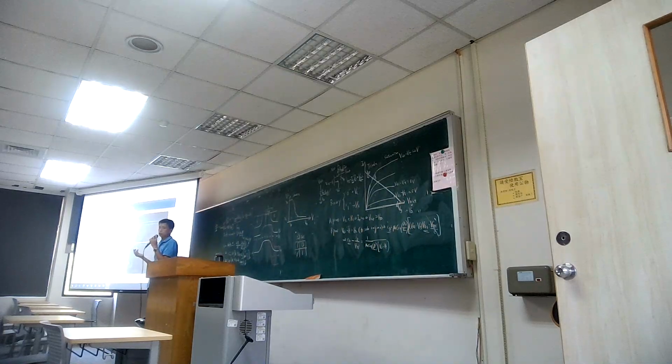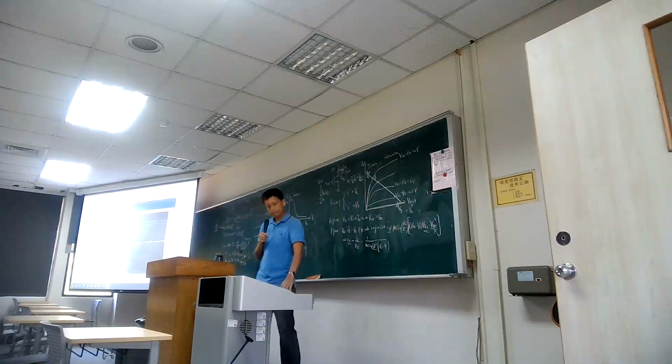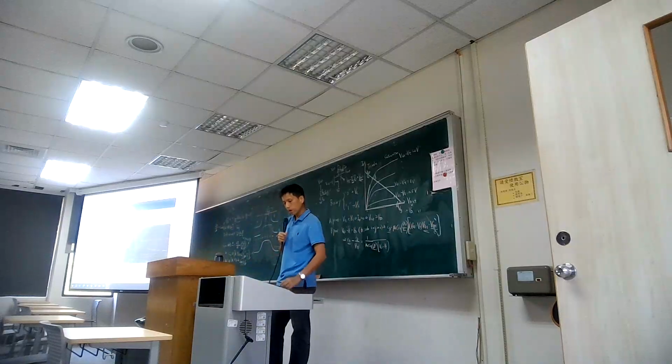Once the VDS is higher than VGS minus VT, it is saturated. That's why we call it the saturation region, because the channel is pinched off. You no longer get more current going through because you have a limited capacity in your channel, even if the driving voltage is high. So you can think that the saturation current is just proportional to VGS minus VT squared.